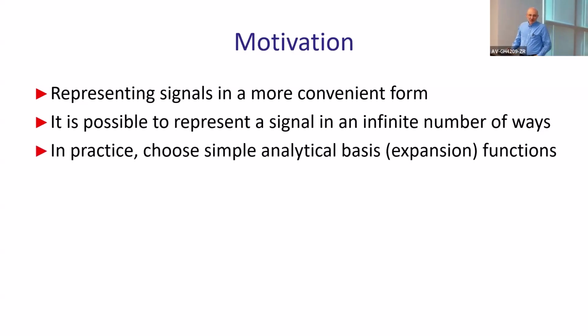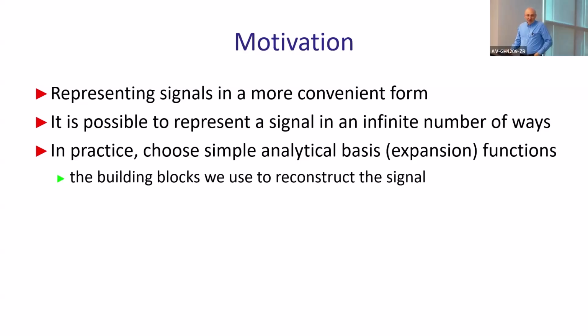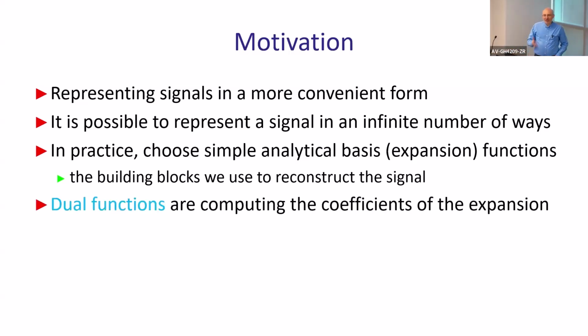So in practice, typically you use simple analytical functions like exponents, sine waves, polynomials, that kind of functions, because they are easy to deal with and also have some practical intuition behind them, like how they look and what it means to have a particular frequency. And we will use them as building blocks for the expansion of our signals. All right, as I mentioned, dual functions are just the formula for computing the coefficients of that expansion that you have.